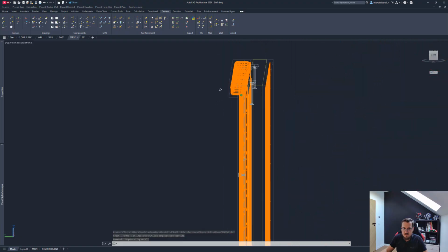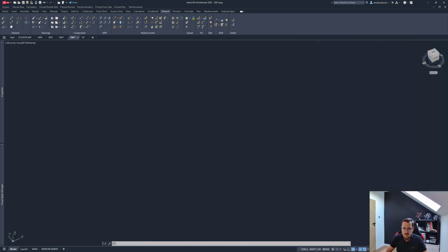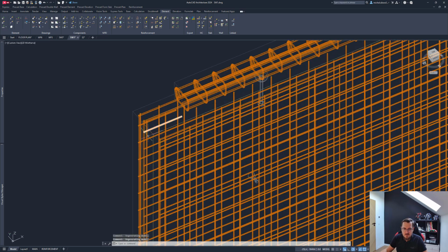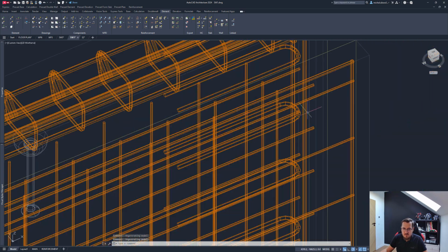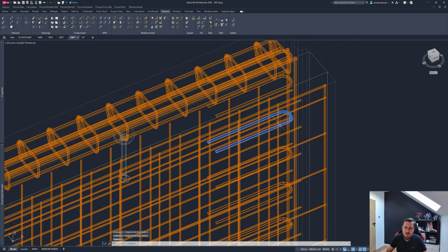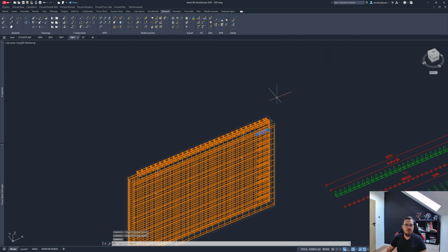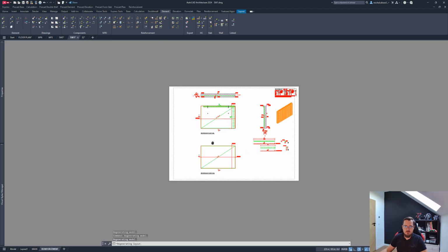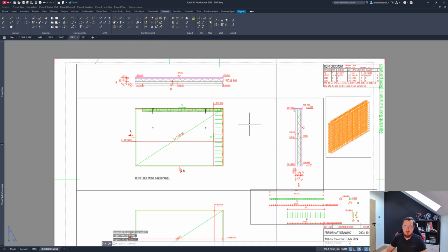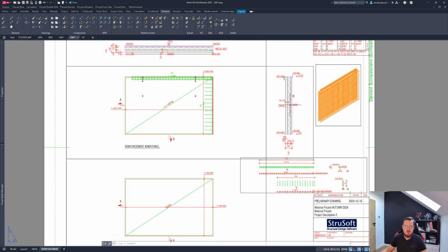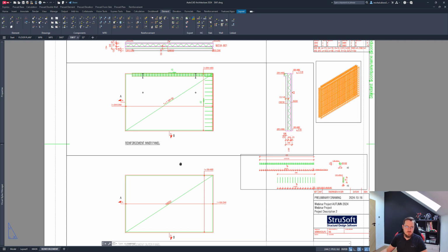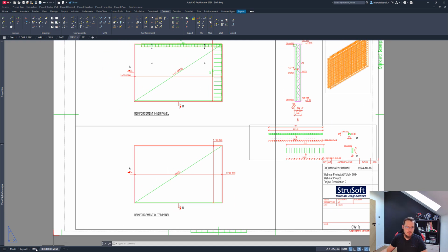So that's the panel thickening reinforcement. You can verify that it's there. There's also the, no, that's not this one. That's the inner panel additional end cap reinforcement for you as well. So if you go to the reinforcement view drawing, you've got all the reinforcement, you've got the groups, you've got the schedule, you've got the 3D view as well, and 2D views for inner and outer panel.